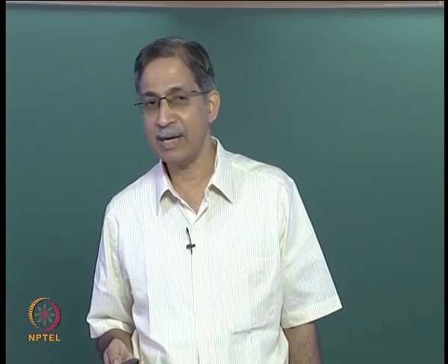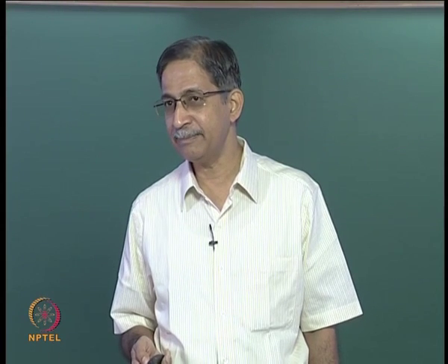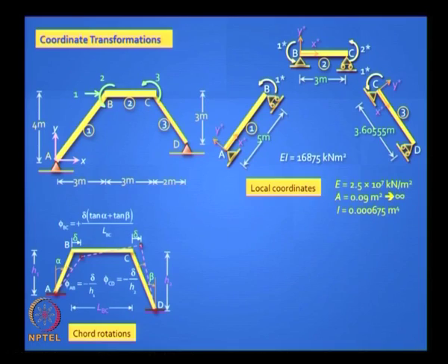I first need to write down my TD matrix, TDA matrix. Will you try that? Okay, to do that you have to be very careful. When you are dealing with sloping legs, you have to correctly express the chord rotations in terms of the sway. So the displacement D1 corresponds to the delta in this figure, right?